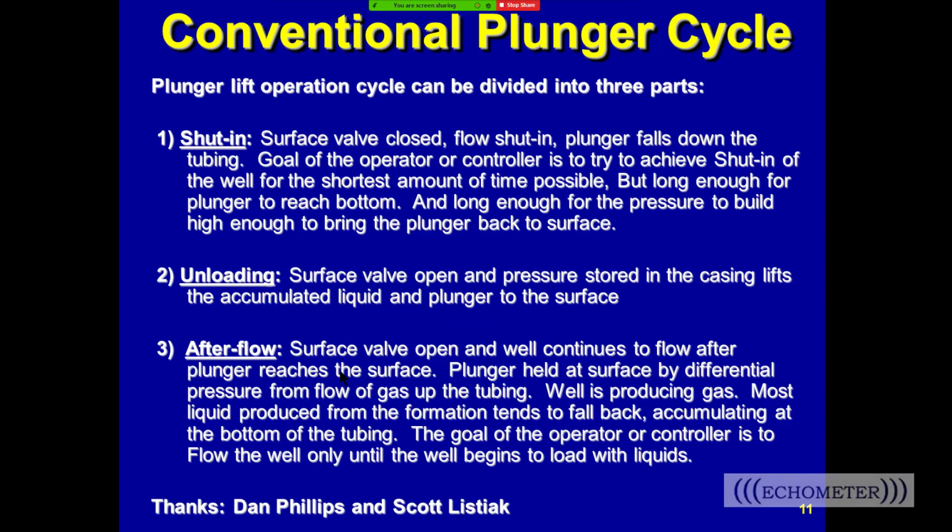Now, when I talk about the plunger lift cycle, I'm thinking about a conventional plunger cycle divided in three parts. The well is shut in by the controller shutting the motor valve, and it's shut in for a sufficient time so that the plunger can fall from the surface all the way to the bottom to the bumper spring. And during that time, we want the casing pressure to build to a pressure that's high enough to bring the plunger and accumulated liquid back to the surface. So that's what I call the shut-in time. And in fact, that's the first time it was defined to me by Dan Phillips. I've stuck with that definition.